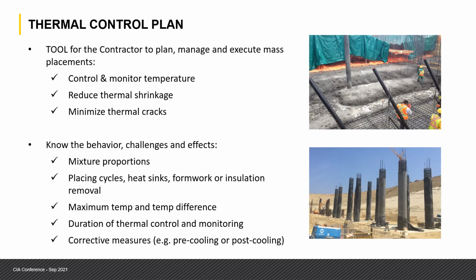As part of the discussions with mass concrete, it's important to understand thermal control planning. Thermal control planning is a tool to manage and execute the mass placements. It helps you understand the behavior of concrete and the challenges. And then once you understand the behavior and the challenges of the concrete, and how you're going to place it, and the temperature limits and the measures that you're going to use to protect concrete, then you can provide a plan that helps you control and monitor temperatures, reduce thermal shrinkage, and minimize thermal cracking.